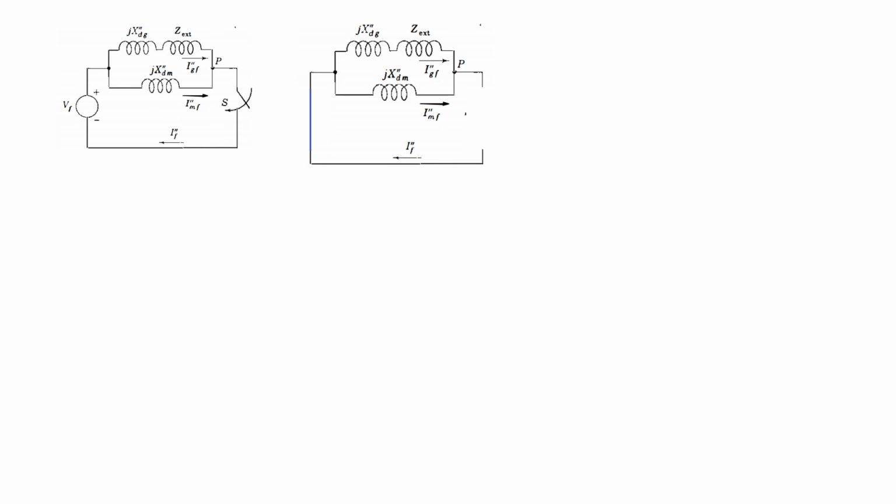So, as you know, for Thevenin's we need to calculate the Thevenin's equivalent impedance. So we short the voltage source and we look from this point. So Z Thevenin is the parallel of these two branches.